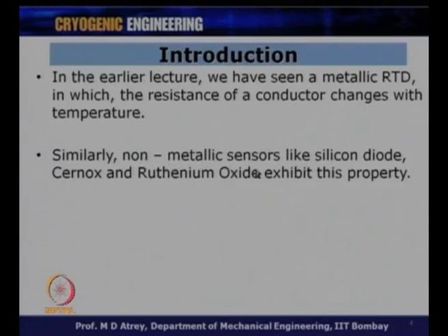Non-metallic sensors like silicon diode, Cernox and ruthenium oxide also exhibit these temperature dependent properties, where resistance changes with temperature again.